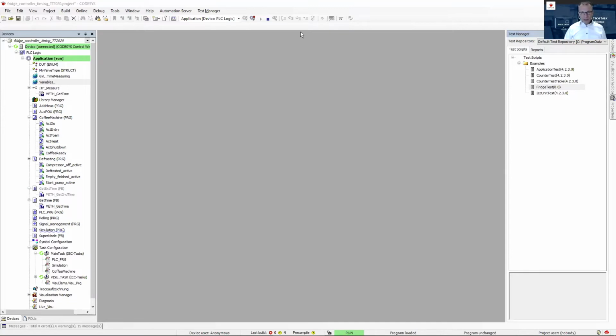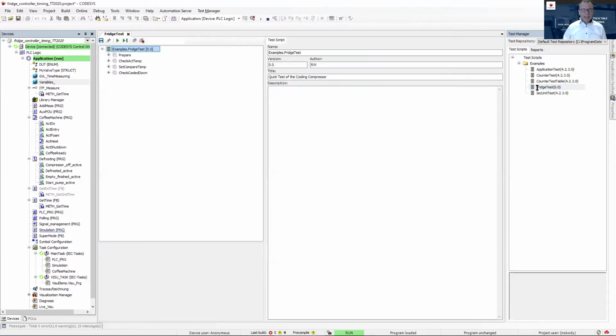So it's time to answer some questions. Does it run tests under CODESYS IDE or on the runtime at the controller level? Now for this first test method where I have this dialogue-oriented tests, it's like I would sit in front of the CODESYS development system and do, for example, changing the values as I did right now. So it's like performed from outside with the development system. We will see in a minute that there are other possibilities too.